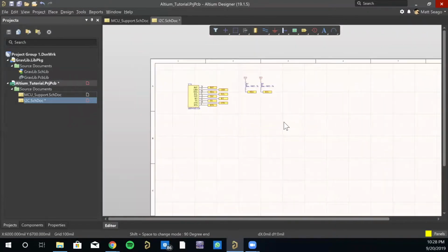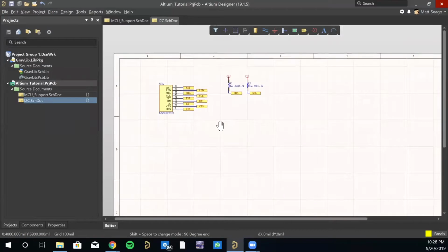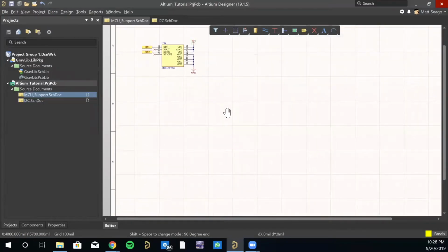Okay, cool. So now I'm going to concern myself with actually creating, let me just save everything, the power that'll power everything. I'm actually going to do that on this page. So I want to create 3.3 volts. I'm going to do this perhaps a little differently than you might ideally do it. A perfectly appropriate voltage regulator for this little board we're making would be just a little low dropout, SOT 23, whatever.